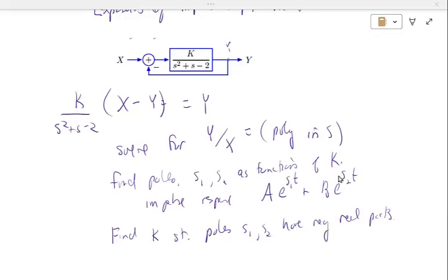Now, before I go on, I would like to mention 2 points that might be confusing. Previously, when we did the system diagrams, we didn't put a Laplace transform inside. We had blocks like the integral block and scalar multiplication. But Laplace transform is just the same thing. Just think of 1 over s as an integral block. Right?